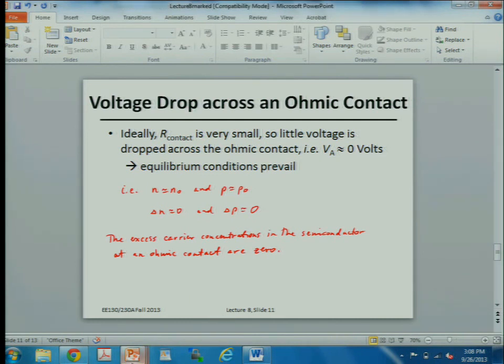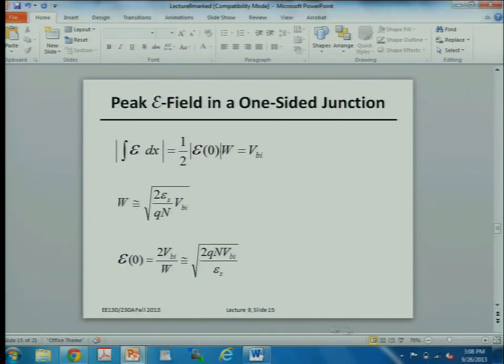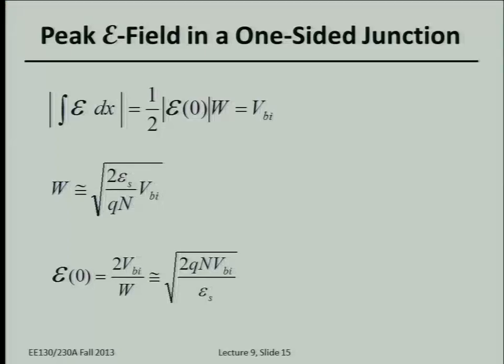Okay. Anyway, I forgot how I got on that topic, but we'll go back. Oh, yeah. Electric fields. In modern integrated circuits, they can be very high and approach the breakdown field of the material. So it is important to keep track of how high the electric field is at your junction, because if it's too high, your junction will break down, and we'll talk about that maybe next week in terms of the breakdown phenomenon.